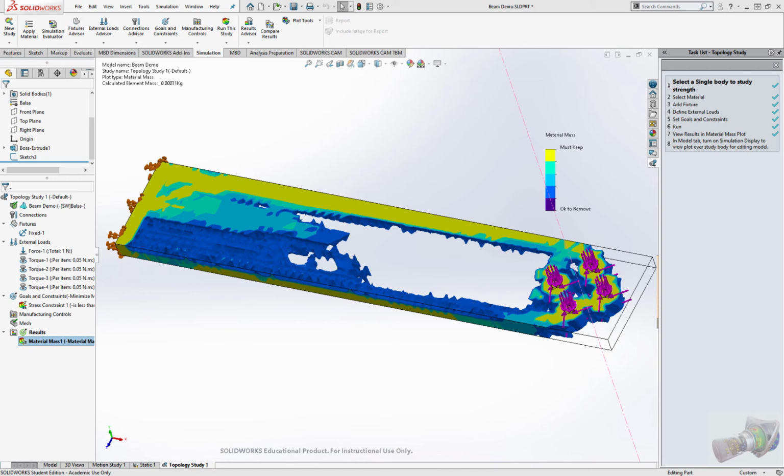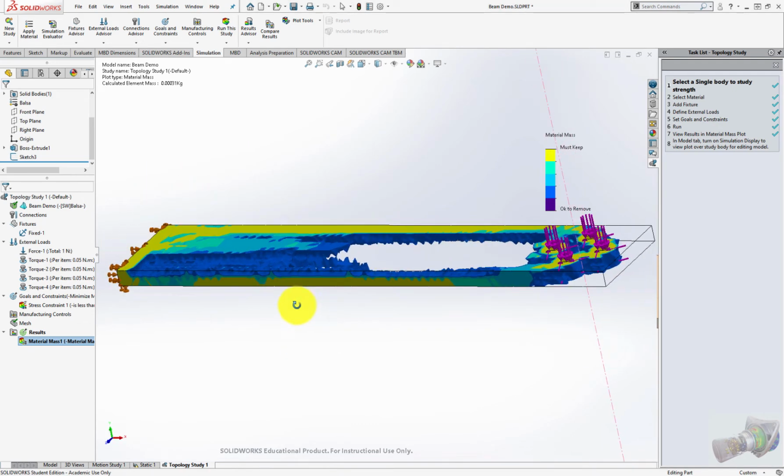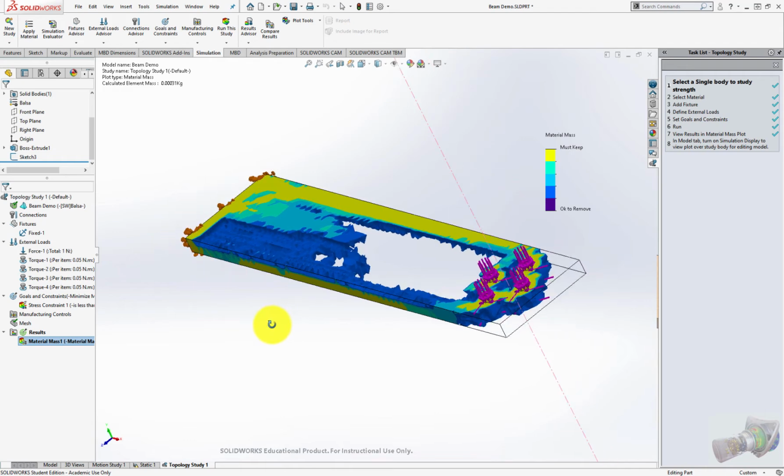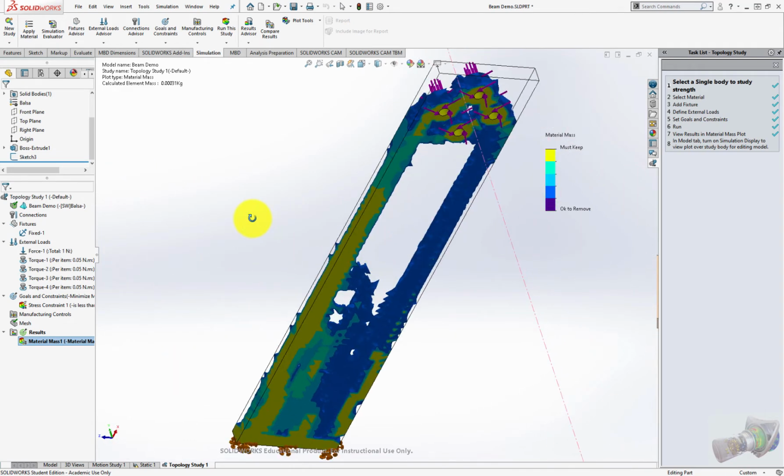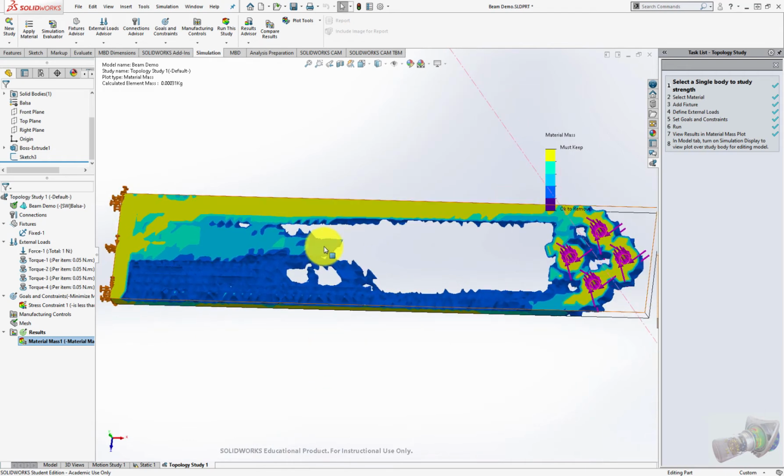And we're back. The simulation has finished, and as you can see, we have something that looks pretty ugly. And that's pretty normal for a topology optimization simulation. So if I'm looking around here, what I see is a big gap in the middle, obviously, that huge hole in this midsection. I see over here, it looks like it's kind of rounded off these edges,